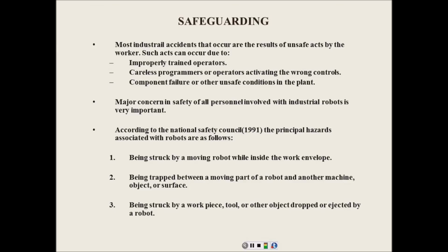So these are gripping things, and sometimes the workpiece itself might be defective, and it doesn't have the exact parameters that the robot needs to grip onto. And it didn't get caught when it came into the work cell. The robot picks it up and drops it, or the robot slings it. That's why they like these fences, because fences help protect you.